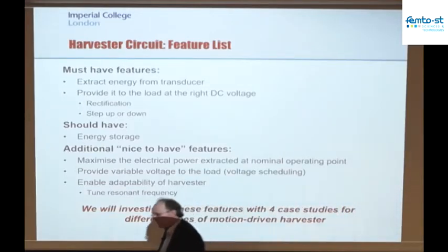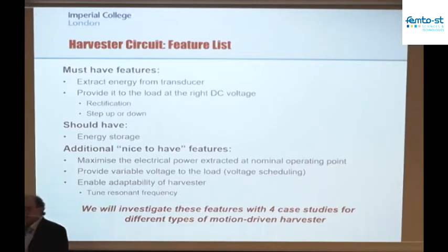If we want to have a resonant device, and we might want to have a resonant device, as I said, if the vibration is much smaller in amplitude than the size of the device, we get significant benefit from resonance, but only if we're operating at the resonant frequency. So what do you do in your car if you're going to drive at different speeds and the frequency of excitation is changing all the time? It'll be a different frequency of excitation if you're doing 70 miles an hour on the motorway to if you're doing 10 miles an hour in town.